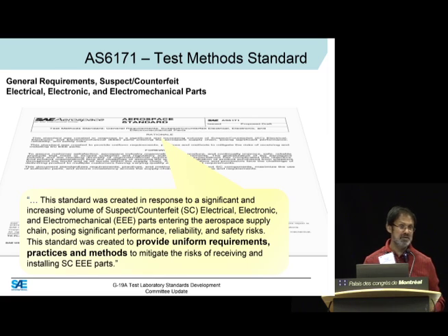But outside of that one, even if the part passes all the testing, I cannot for sure tell you that this part is a counterfeit or not, because not all the tests that we do can 100% verify. There's no way a test lab can do 100% electrical testing for the data sheet and have all the patterns and all the design simulations that the OCMs have. All you can do is the best you can do, provide the best coverage you can, and have some level of confidence. So that's all we're doing, is we're verifying, not authenticating.